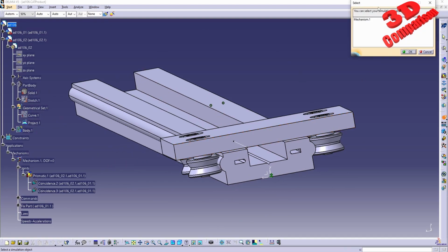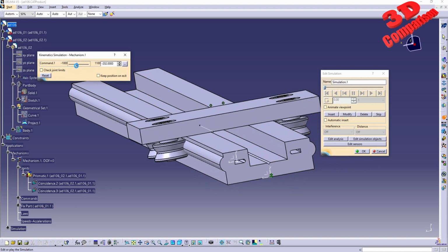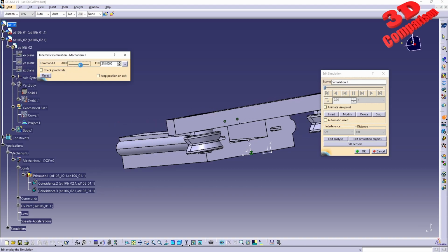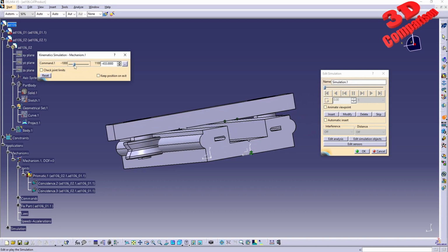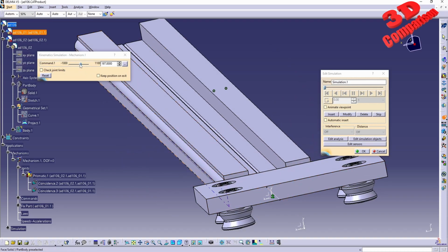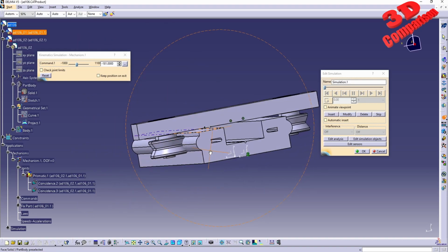And if I will start the simulation of the mechanism, I know that I need to add over here minus 1000. And we're gonna see how that rail will now simulate, and it will maintain that offset. So keep that in mind that in cases like this, you can just create an invisible part that will act as that support for the prismatic joint over here.